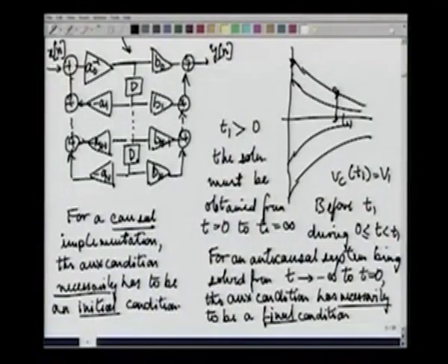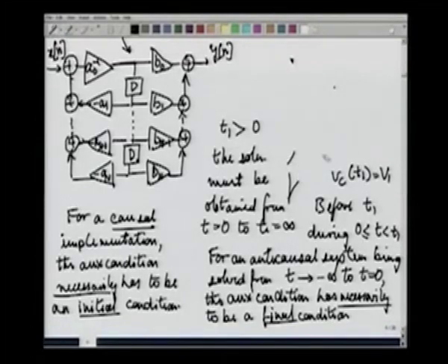So, going back to this block diagram, why did I draw this? Very simple. You have all these delay blocks over here. Suppose this is a causal system that I am trying to implement, and I want to understand what the values of the system are at n equal to 0. Let me just erase this part, now that we are done. At n equal to 0, these amplifiers do not take any time to compute. What will we get as y n?